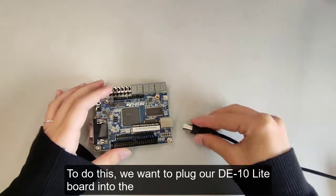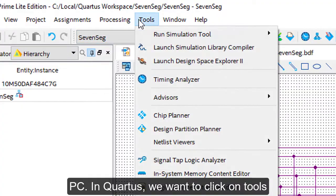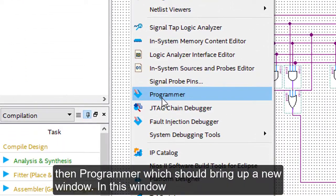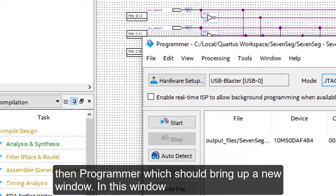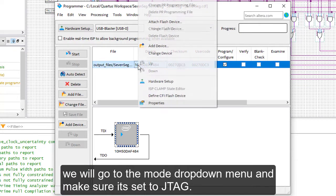To do this, we want to plug our DE-10 Lite board into the PC. In Quartus, we want to click on Tools, then Programmer, which should bring up a new window. In this window, we will go to the Mode drop-down menu and make sure it's set to JTAG.